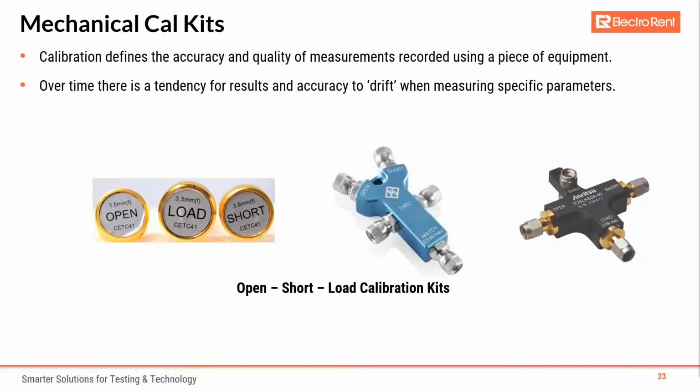Calibration kits, such as mechanical cal kits, offer the cheapest, most customizable, and highest frequency choices for calibrating a vector network analyzer. Depending on the OEM VNA that you are using, you can use the available cal kit from that OEM. Cal table standards are required to be installed in the VNA before proceeding to use a cal kit. In most cases, the standards are pre-installed.